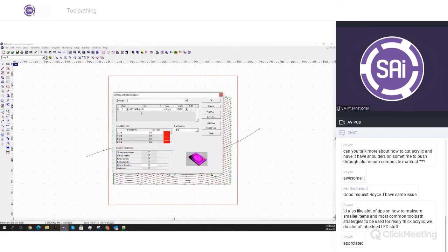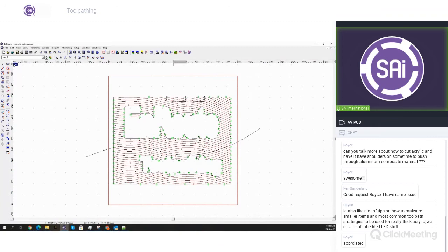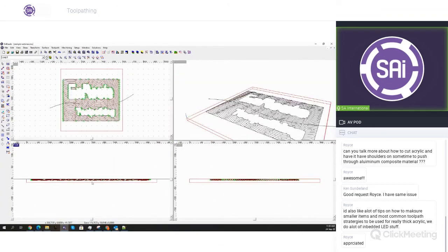And here I would have used the 3/8 inch ball end mill, which is about 9.5 mm, I think. And I have simply set it to follow the contours, as my texture made it so that the contours are waved along the design.